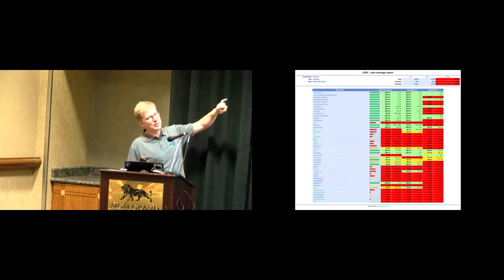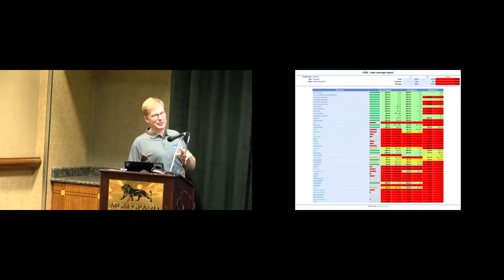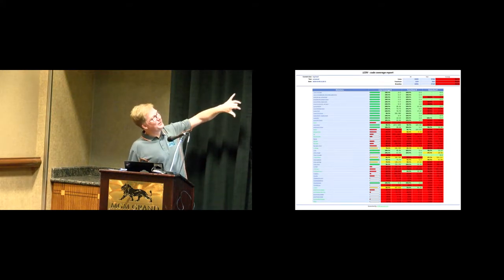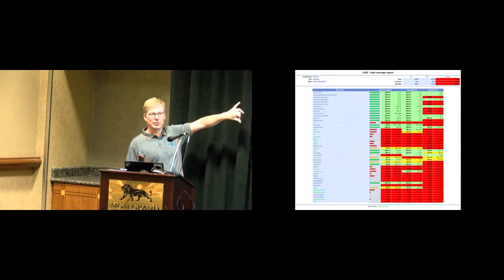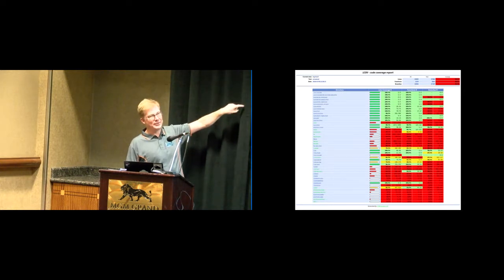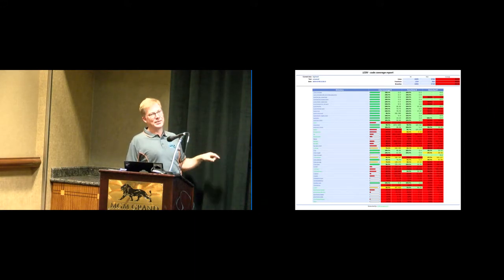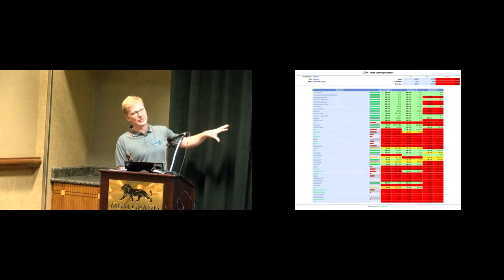So we can run our firmware test suite, which the big reveal will come later. But we can run our firmware boot and runtime testing as well as unit tests and get code coverage reportage out. So not only do you have an open source firmware stack and we'll have an open source test suite, but you can then go and look at the code coverage of running this against actual hardware and work out, are we actually testing all the things we think we're testing, and have good targets of where to add extra functionality.